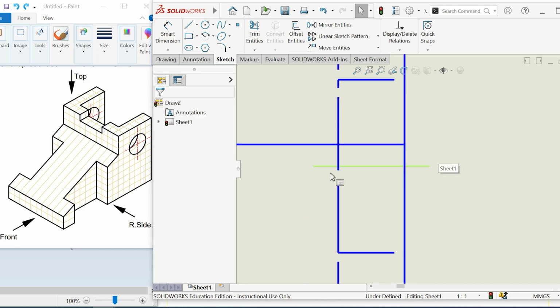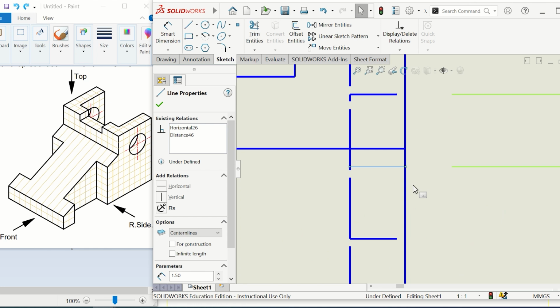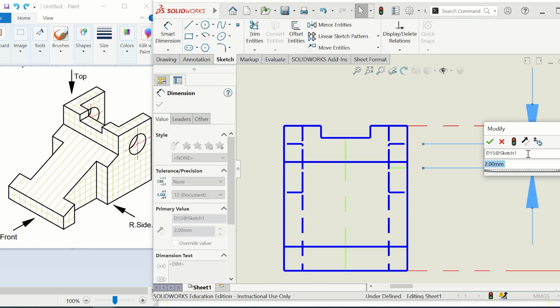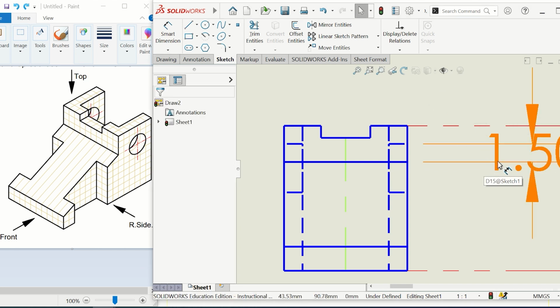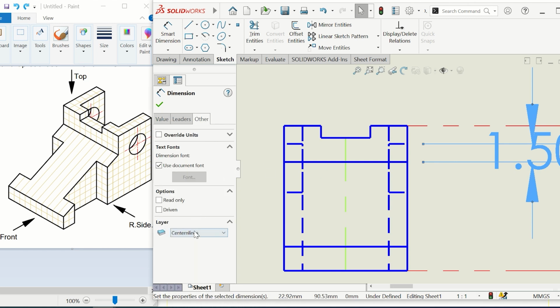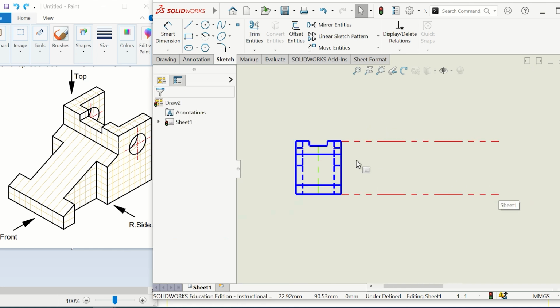So this center line, okay. However, remember that this distance is 2, so it has to be 1.5, and this line will overlap with a visible line. Some people might decide not to draw it, which is fine, but I'm showing you, should you want to draw it, that's what you should do. You can draw the other one, the mirror one, but for now, guys, I'm just going to go on, because these are less important than what I'm going to explain now.